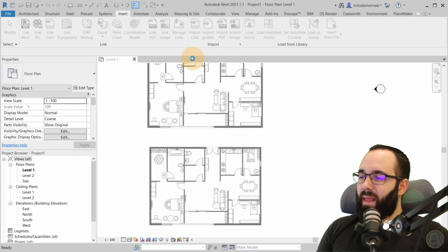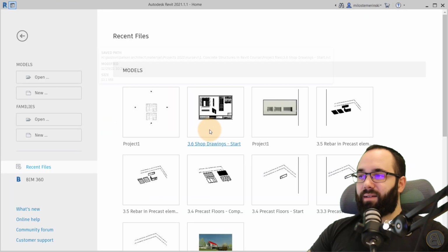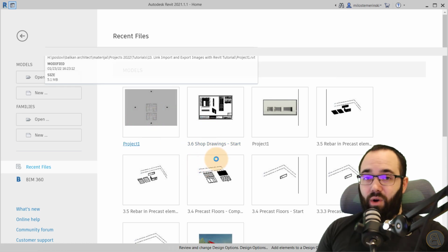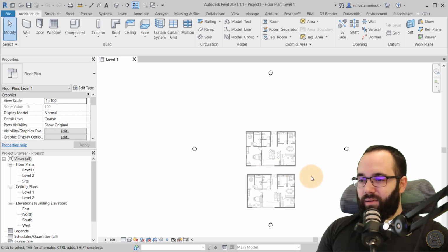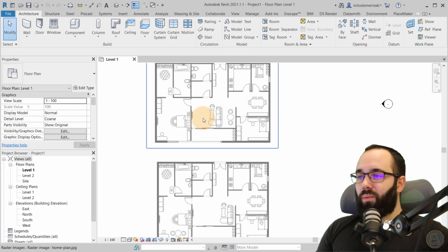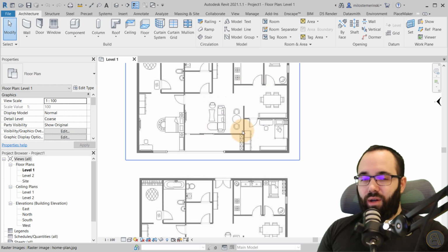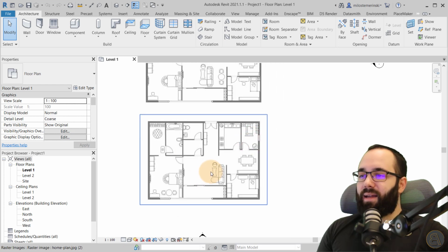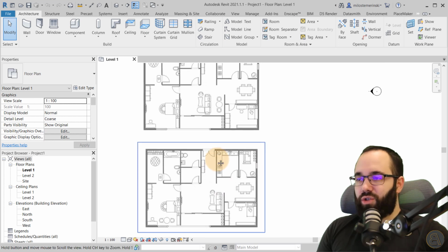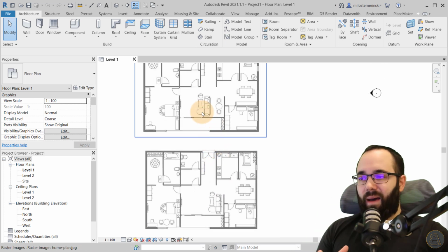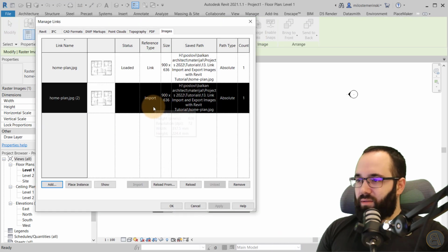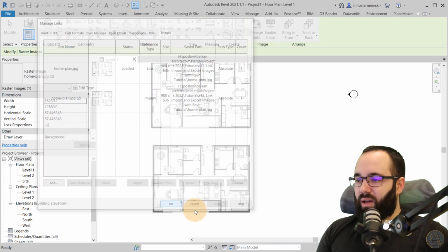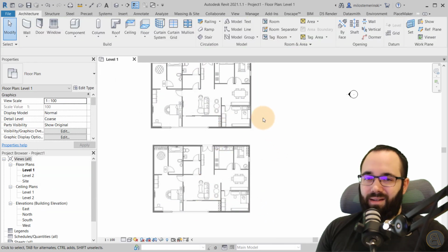That's okay. So I have saved it, and now if I open that project again, now the link, as you'll see quickly here, the link will update to the change of the image, and then here the import did not change. So just with closing down the project and opening it up again, the link did change, but the import did not. But again, it's an easy fix with an import, so just go Manage Links, Reload, Apply, OK, and as you can see now, there's that change.